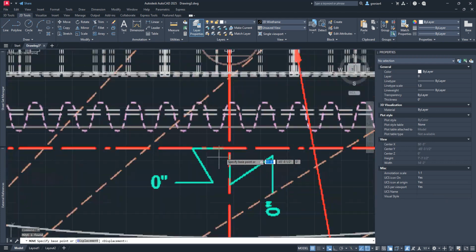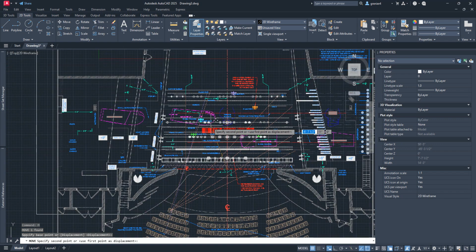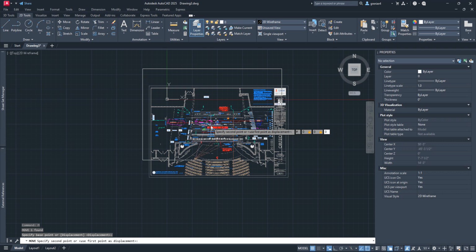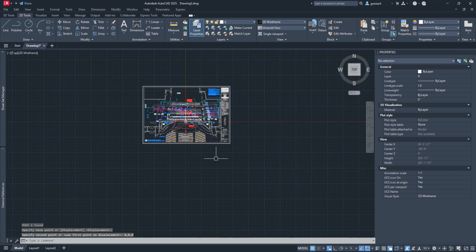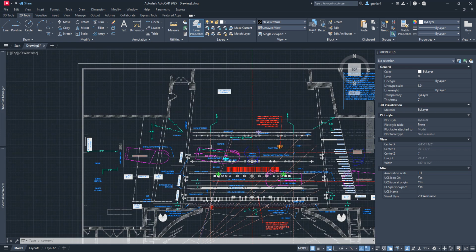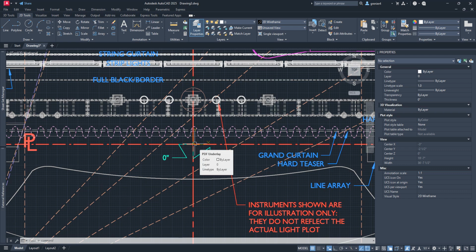So I'm going to do that again. I'm going to move. I'm going to choose that point. And I'm going to type hashtag 0, 0, 0. And you can see that there's like a line going over to the origin. I'm going to hit enter. So I told it to move that location to the absolute coordinate of 0, 0, 0. And now I have my center line, plaster line intersection right at the origin of the drawing, which is good.